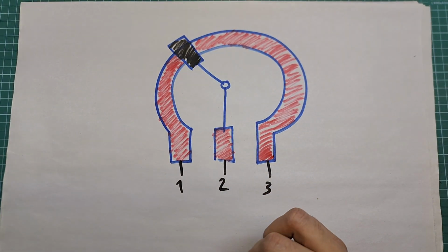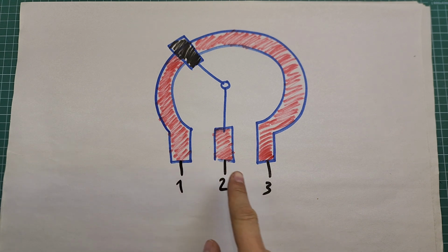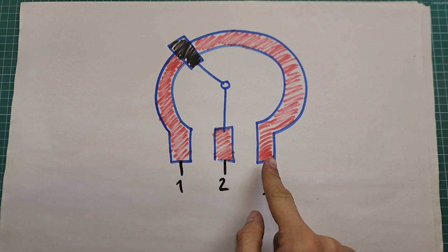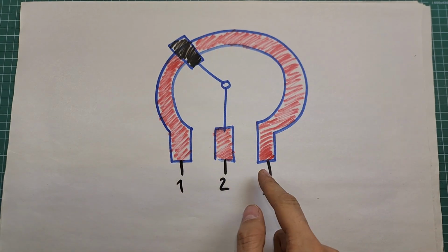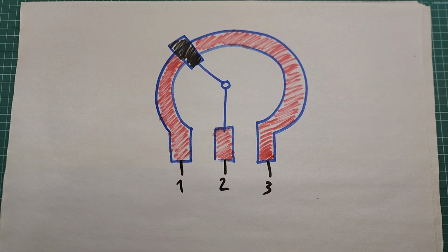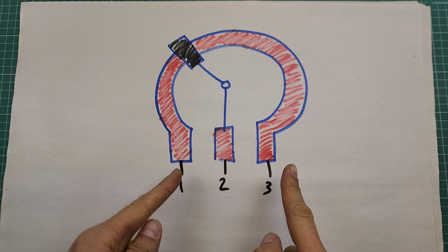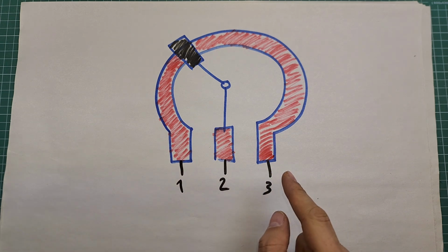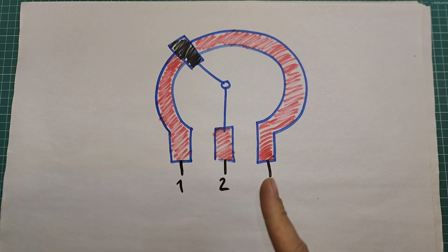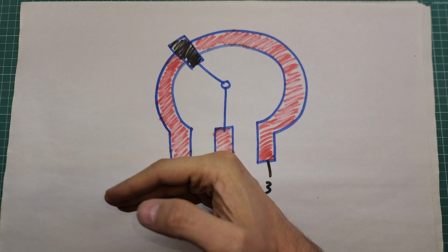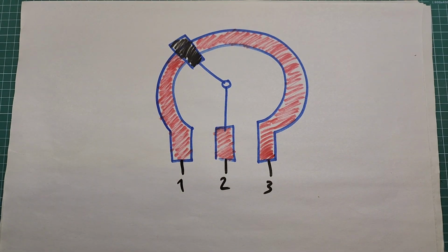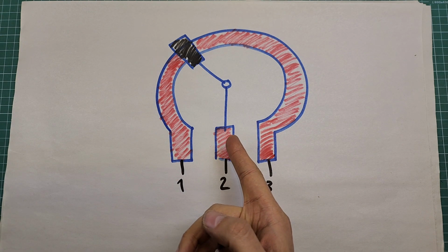The nominal resistance of a potentiometer is the resistance between the outer terminals, I mean pin 1 and 3, which is always constant and equal to the potentiometer's nominal resistance. Potentiometers essentially have a fixed resistance between the outer two terminals. The middle pin is a wiper that slides along the resistive element between the outer terminals, which changes the resistance between the outer terminals and the middle terminal.